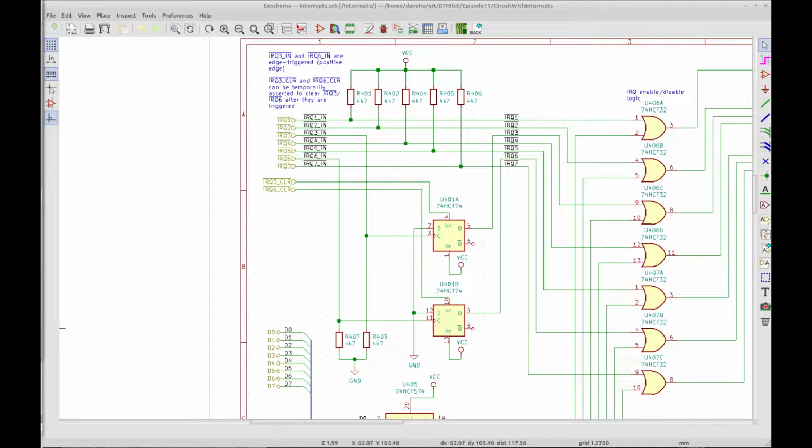When the software interrupt handler has handled the condition signaled by an edge-triggered interrupt, it asserts the set input on the appropriate flip-flop using the IRQ3 clear or IRQ6 clear signals. These cause the output of the appropriate flip-flop to return to generating a high, non-asserted voltage.